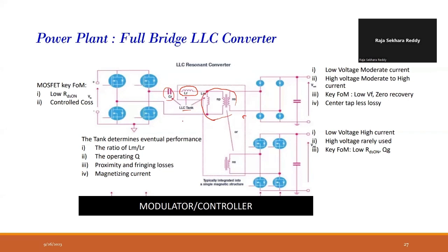Okay. And here, basically, the focus is on getting ZVS switching. In ZVS switching, of course, the losses are less, and that is why the LLC converter is very popular. It is a DC-DC converter, and it is used in electric vehicle battery chargers.